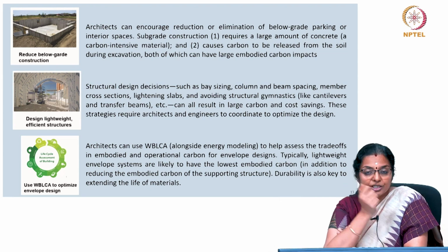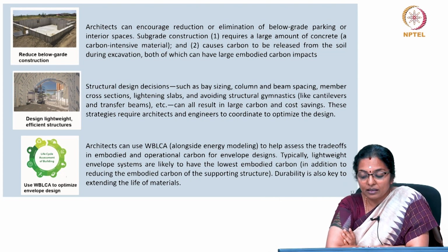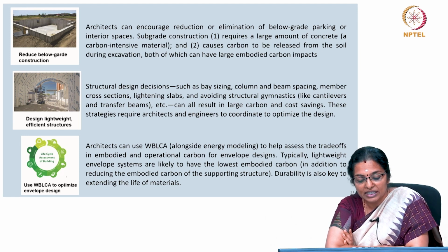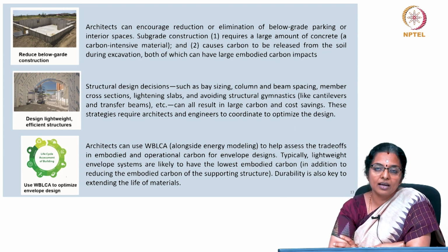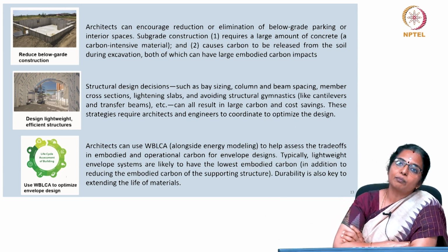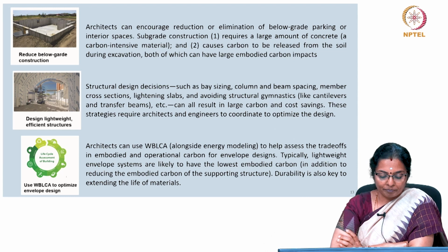Structural design decisions such as bay sizing, column and beam spacing, member cross sections, lightening slabs, and avoiding structural gymnastics like cantilevers and transfer beams, etc., can all result in large carbon and cost savings. These strategies require architects and engineers to coordinate to optimize the design, along with an awareness by the client.